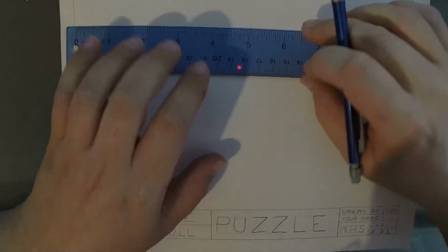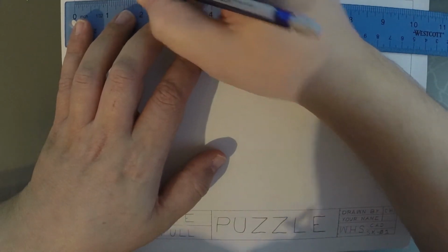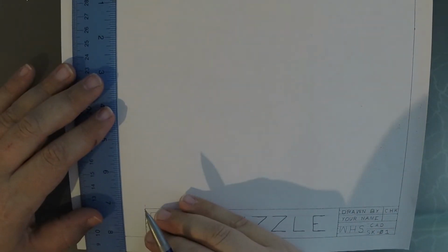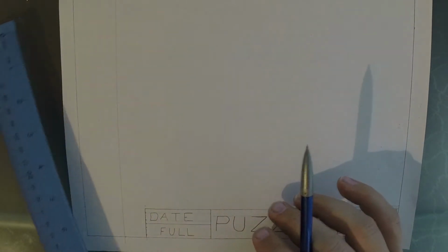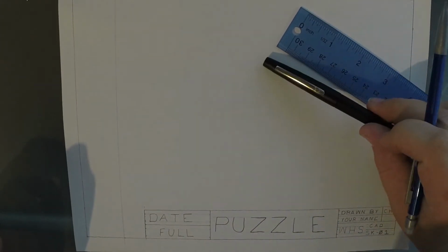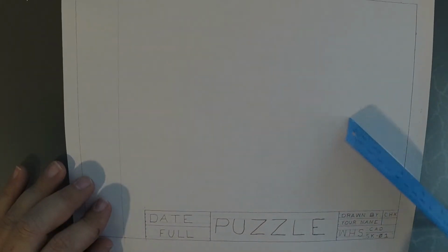And as we just showed, we are going to be centering the puzzle inside of that space. So our horizontal gap with construction lines is going to be 1 1/4 inches. So I'm going to make a mark at the top and the bottom, and I'm going to draw a construction line, which my pencil marks from here on out are going to be construction lines. And then I will use eventually my black felt tip pen for my object lines. It's just easier to show up on the camera here.